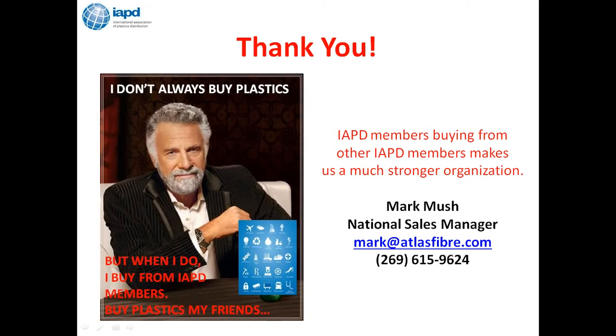Should special safety or respiratory measures be taken for the machining process? No more than your regular exhaust systems for sawing. You definitely want to get this exhausted as quickly as possible, just like any other sawdust that you'd be creating. But there are no specific hazardous health issues associated with any of these.